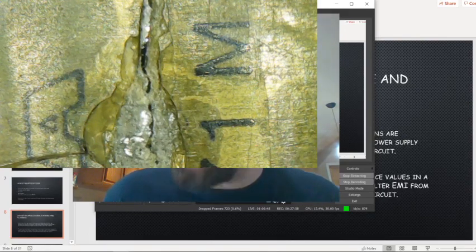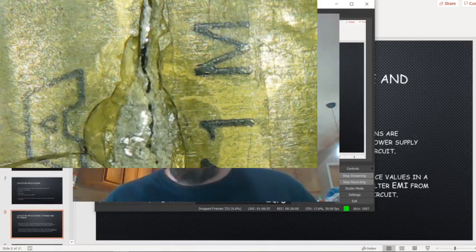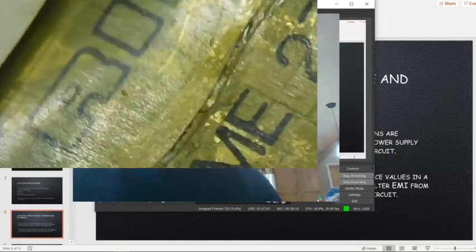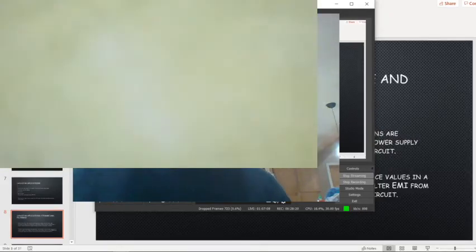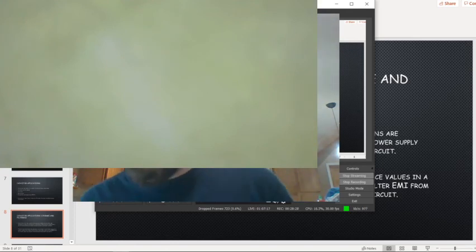It can short out your device, and it'll literally short the lines that it's across or to ground, and it's a very, very bad day. Lots and lots of things from the 1980s have these in them. Just so you guys know, if you ever see these, they're called RIFA, R-I-F-A. Even if they don't look too bad, get rid of them. Garbage. In the bin.